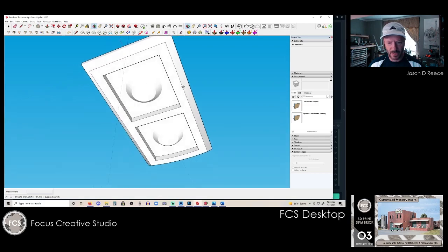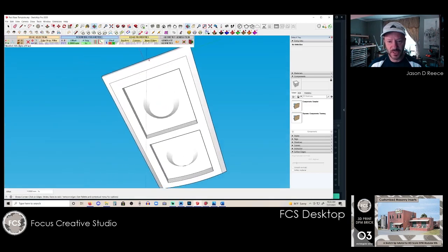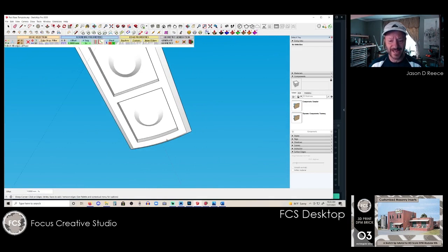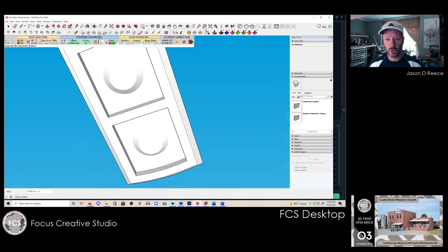Now the second thing we want to think of is, we know this is the part hanging off the build plate. We know this is the part down here that's hanging in the resin every time. So it drops down each time and sits in the resin against the FEP. The light comes on, cures the next layer. That's happening down here. So then it raises up. So anytime we have a lip like this, that resin is going to have a tendency to pool. So we're going to go ahead and put a bevel on this edge.